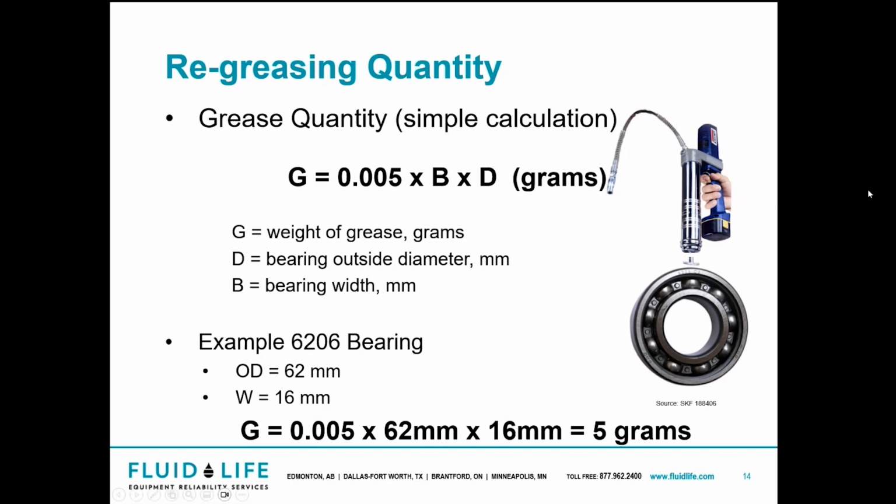So when it comes to calculating grease, the quantity is based upon the free volume within a bearing. What I mean by that is you have your bearing and its housing and all that air space there. You're only supposed to fill that space about a maximum of 40%. So when you keep adding another shot of grease, it's fine, and then it starts puking out the seals, well, you're overgreased.